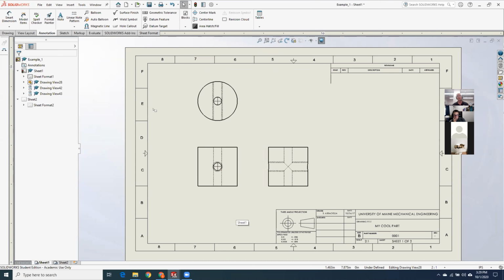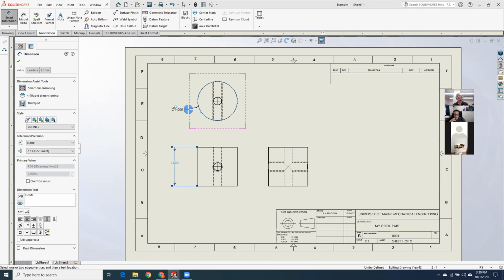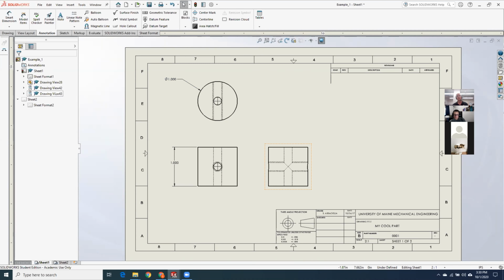Okay. Generally, what I like to do when I start off dimensioning a part, the question that I always ask when I go over to the material rack is, how big a piece of metal do I need? You know, how big a piece do I need to get the part that I want out of the chunk of metal? So I always start with the overall dimensions. So the height, and in this case, diameter. So that tells me what I need there.